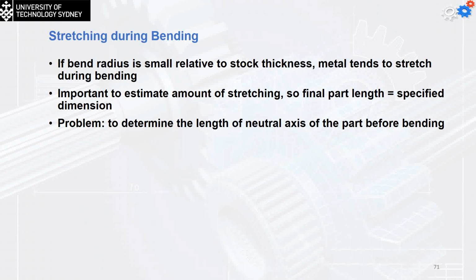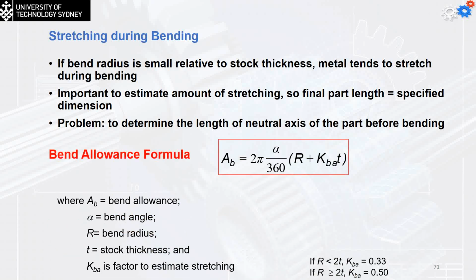One of the effects that will happen during the bending is what we're going to see here. Some of the energy, the elastic energy, will be stored in the material, which causes the spring back effect. So we thought that we're bending the part, that's okay, but as we release the force, it's going to spring back.